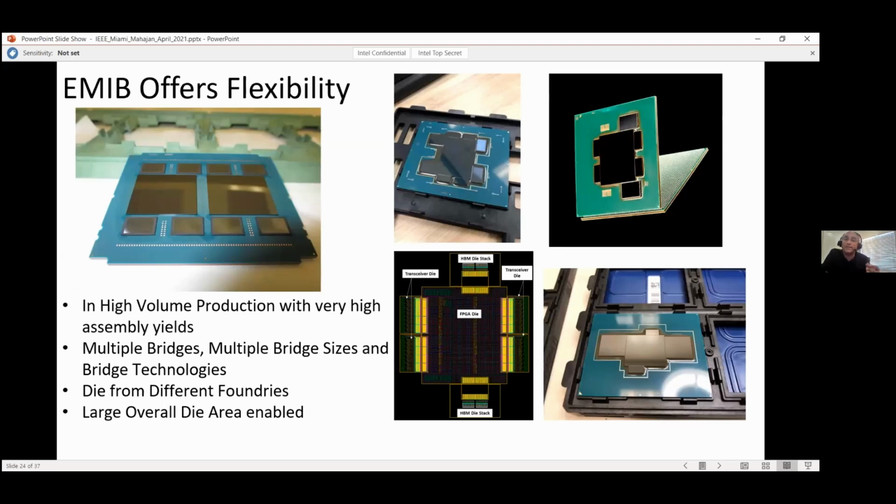This was always a concern with people, are you taking up more area? But it turns out that the yield advantages of reducing die size overwhelm the increased area due to that interconnect. The reason I asked was I was listening to the presentation from Raja, and he was stating a number close to 20%. It depends on how many of them you put. When you say Raja, you mean Raja Swaminathan from AMD. Right. They're not using fine pitch interconnects. That's probably why they are higher. They are coarse pitch, more in the 110 micron pitch. And they are SerDes interfaces. The ones we are talking about are digital parallel interfaces, so they're much, much simpler. I see. Okay. Fair enough. Thank you.